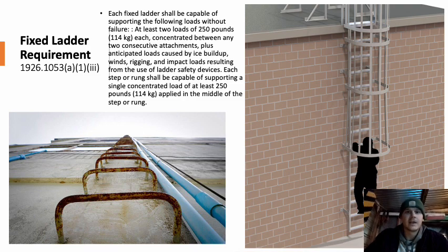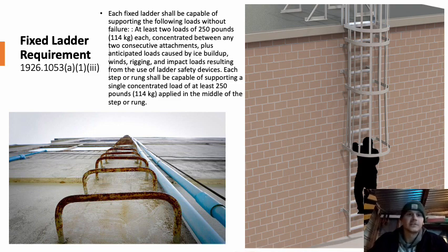So each of these steps needs to hold 250 pounds, and if they're pretty tall, they're going to have sections. So each section needs to be able to hold at least 2 loads of 250 pounds, so 500 pounds in one section for each section.